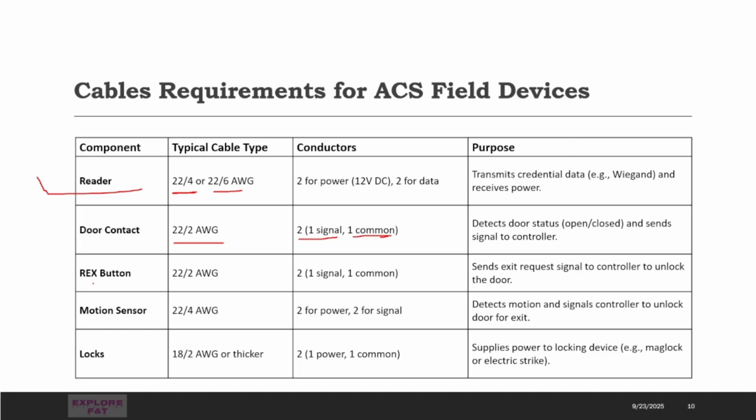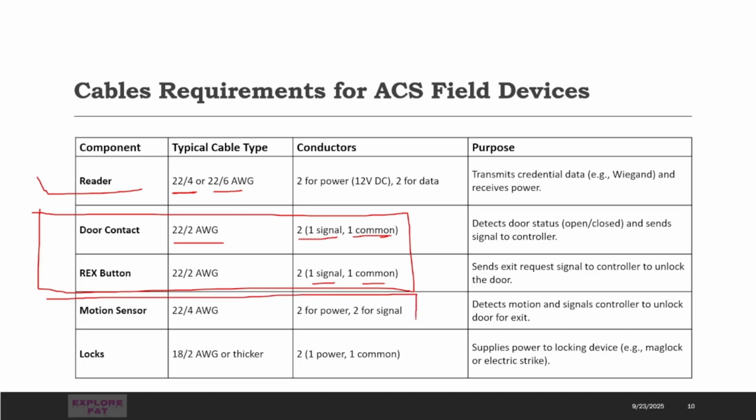Okay, now the REX button also requires a signal. It's the same as the door contact, which also requires a signal, REX will also require a signal. So here one signal, one common. But for the motion sensor, if you see, this requires power as well.